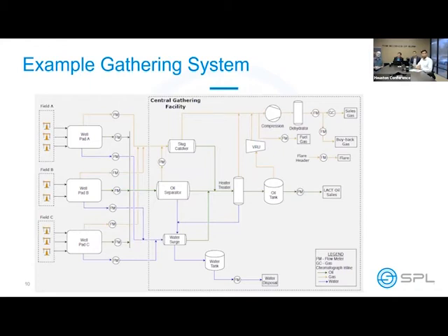During any of this process, we are consuming fuel gas. That fuel gas would be used to fire the heater treater, for example. It could be used to power the VRU or any compression that we may have at the gathering facility. And then ultimately, all of those dispositions would need to be allocated based on either throughput, or they could be allocated through some contractual system that the contracts may certainly spell out.